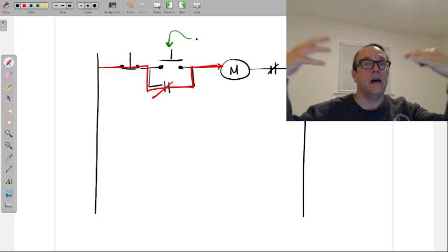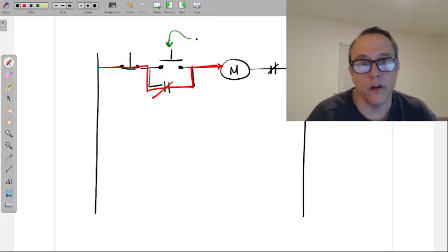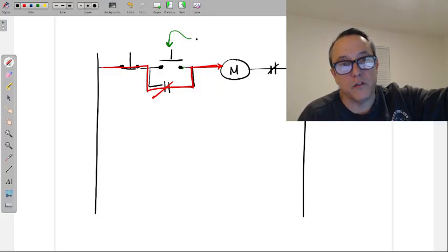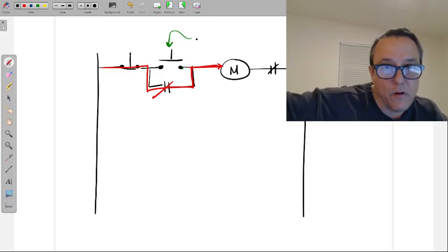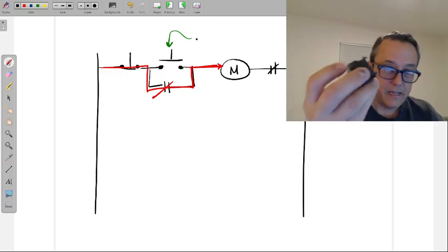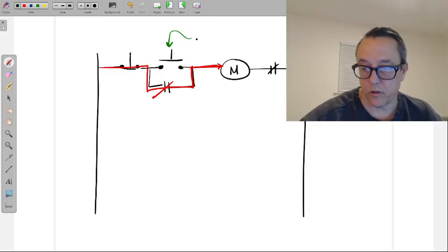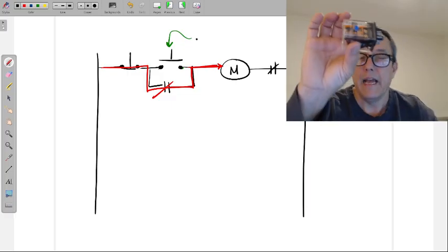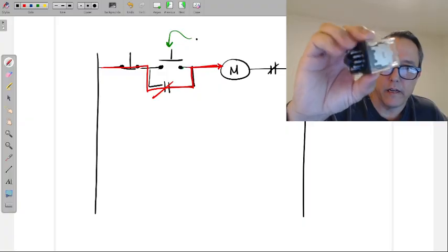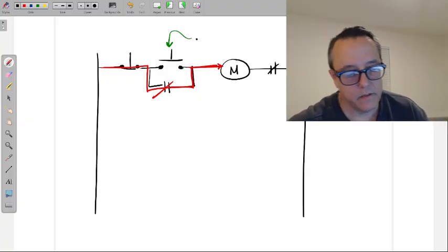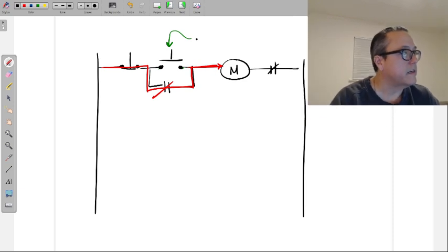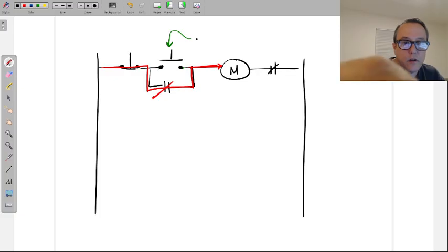So when you have a lot of things going on, a lot of loads being energized, bunch of lights turning on with motors turning on, and etc., you get rid of your auxiliary contacts because they present just a little bit too much of an annoyance to work with, and then you replace it with the control relay. So when you have that, going back over to the circuit here, now we sort of redraw this, all right? We redraw this, I'll get rid of all that.